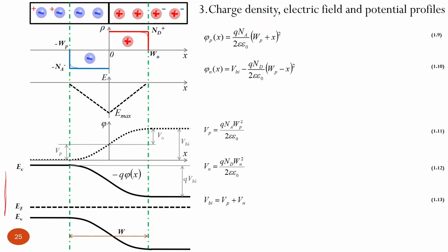First of all, we need to highlight that the band diagram is drawn for electrons. Electrons are negatively charged, so we have this minus Q. When we go from electrostatic potential to energy, we multiply electrostatic potential by the negative elementary charge Q of electrons. That's why the band bending is a mirror reflection of the electrostatic potential distribution.